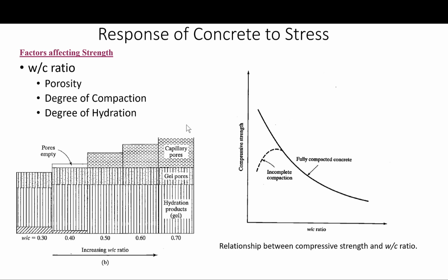While most discussions involving water cement ratio involve compressive stress, tensile strength also increases with a decrease in the water cement ratio, just for your information. So the water cement ratio law, as usually stated, is a simplification of the true state of affairs. It's not really an accurate representation.